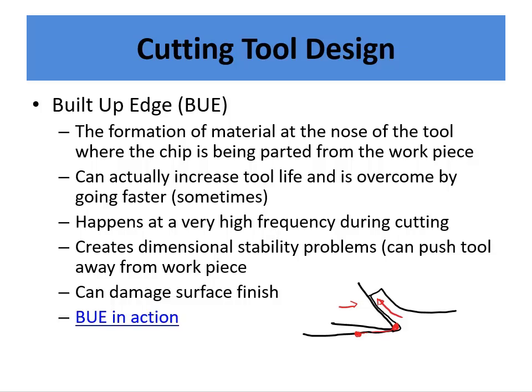And the issue with the dimensional stability can come in because as you're cutting, if you have that little built-up edge occur, it can actually push the tool away, and then the tool will snap back, and that can actually happen with some sort of frequency, and it can cause a dimensional problem. Okay, and also that can damage surface finish because you can drag that lump of material across the part, and it can leave a bad surface finish. And I'd encourage you to watch that video in the notes on that topic.